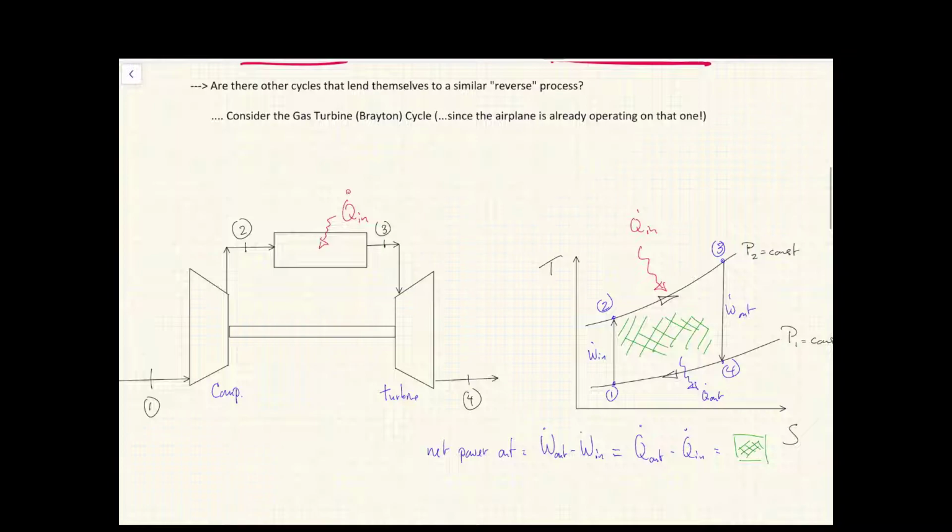Again, I've got my little triangles here that represent the compressor and turbine components of the gas turbine. So recall that the air initially comes in to the compressor. It's compressed to a state 2, at a point where the isobars from the low pressure P1 to the high pressure P2 are somewhat close together, meaning that the amount of work that's required, while certainly not insignificant, is much less than it's going to be further on when we move to the right on the TS diagram.